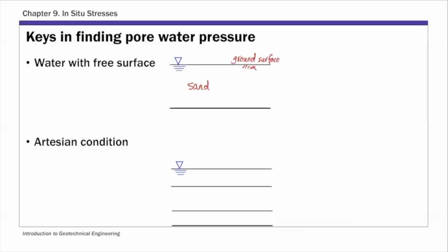So if you have a free surface, and you put a standpipe here, a piezometer or standpipe to measure pore pressure, water is going to rise up to this free surface. Okay. So this is a pretty common case.